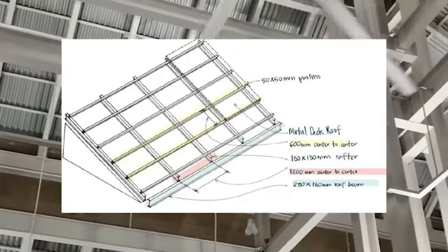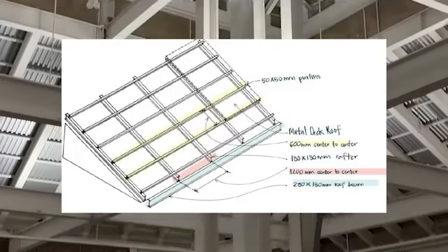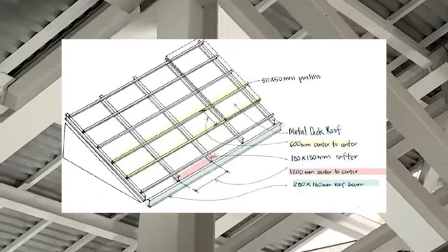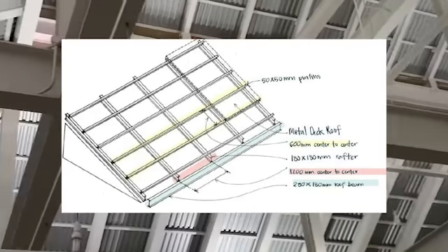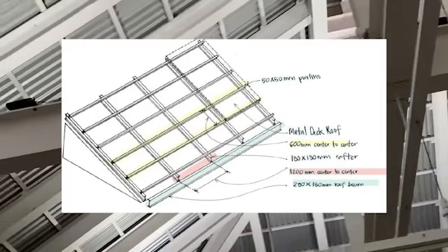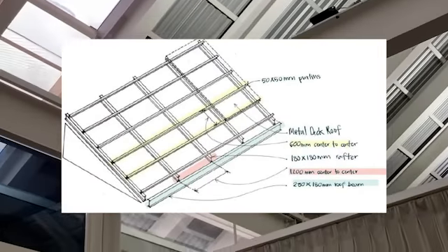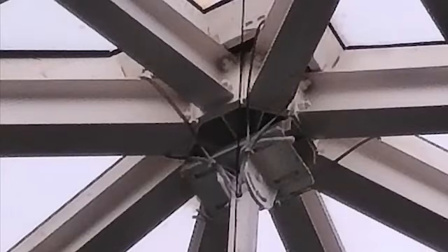The rafter was 180 x 180 mm with 1200 mm to center. Then it is supported by the roof beam at 280 x 180 mm to support the rafter and purlins. There are skylights at the third tier of the roof to give natural lighting into the main prayer hall. Then, the rafter at the Tier 3 roof was connected with a bolted connection.